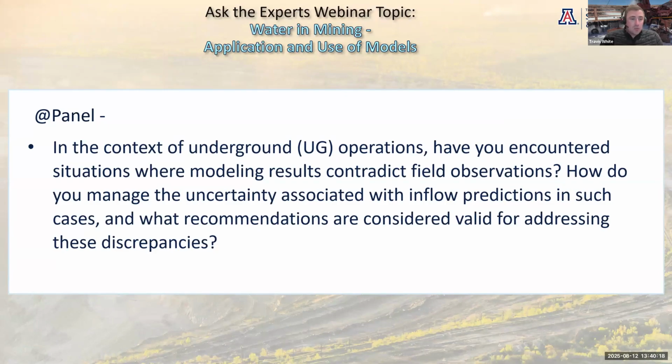A few other things you can do, whenever you do a modeling run, or when you're developing a new mine or sinking a new shaft, is to have continuous monitoring in place. It's pretty good practice to have piezometers around your vent shafts or vent raisers. If you're developing underground stopes or drives, get piezometers in your cover holes, or try and influence the mine design to have dedicated cubbies where you can drill holes from.